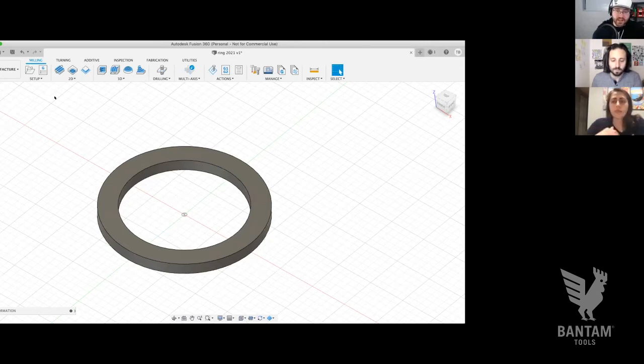With this design, that's perfect, because we don't need to do anything terribly complex as far as how we program things. We're just going to be coming down with the cutting tool from above. We're going to cut out of that metal that he measured, cut down the circle in the middle, and then cut a circle around the outside, and we're going to liberate that ring. And just because you're wondering what happens when you cut all the way through, don't worry, we'll talk more about it a little later, but we're going to fix it down to the bed of this PCB mill with some high strength double-sided tape, which will hold it right in place. So you get rid of all the metal, and you're left with just the ring and the tape that it's sitting on.